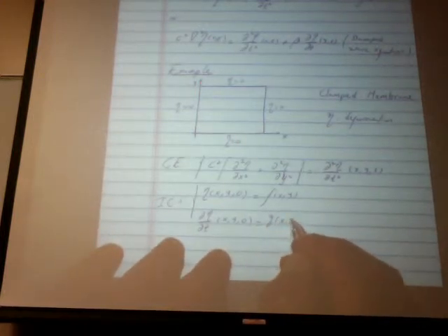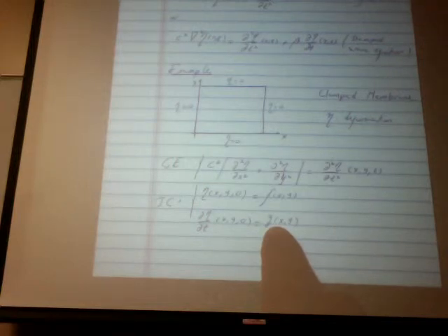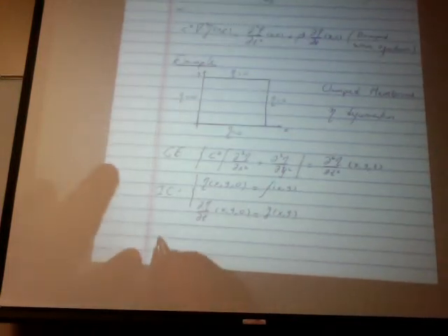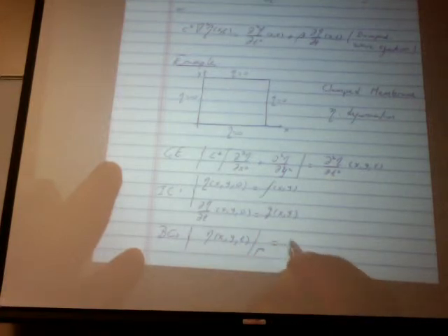And let's say that the initial speed is some other function g of x and y. So let's assume that this is a drum clamped on the periphery, and let's say that the original state is stationary, but then we perturb it with an initial speed. Or we can perturb it with an initial position. We can just hit it in the middle or pull the middle, raise up eta for the deformation to a positive value, and see how it would vibrate. And the boundary conditions, we have eta of x, y, and t at all portions of the boundary equal to 0. So we have homogeneous boundary conditions.